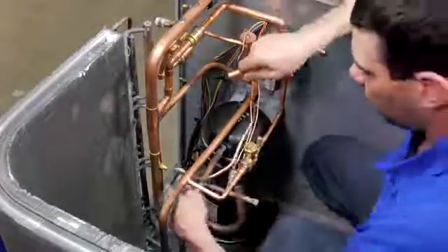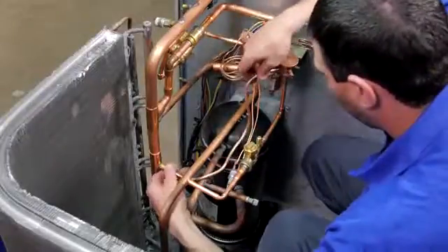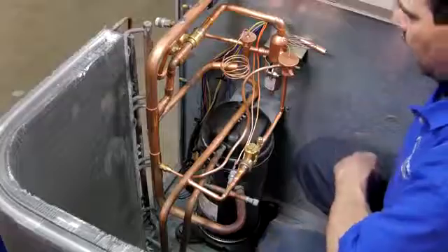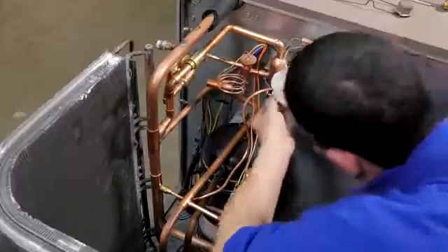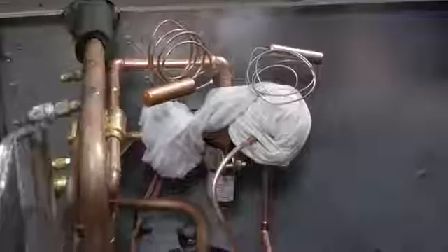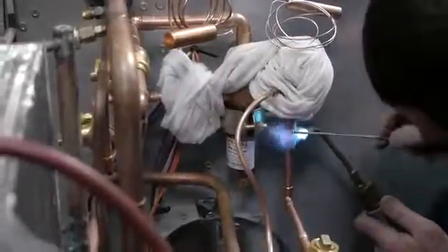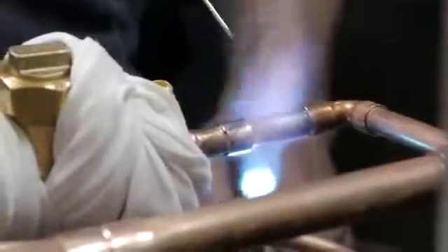Connect the T in the suction line for the external equalizer to the hot gas valve external equalizer port. This is labeled EE on your installation diagram. All APR controls have the 1/4 inch external equalizer port, with the exception of the model APR 410-1. Reference the specification and dimension sheet for connection sizes. The valve bodies are susceptible to heat. Do not overheat them. Wrap them with a heat-absorbing paste or wet rag. Proper brazing techniques apply.